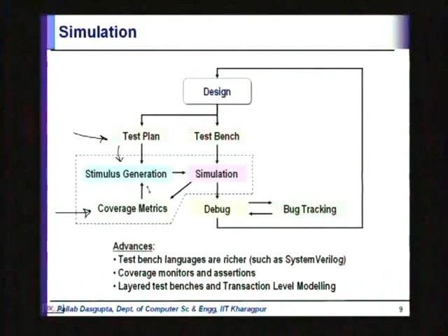It can even do things like state coverage, whether every state bit has toggled once, that is toggle coverage. Whether certain wires have toggled at least once during the simulation, that is toggle coverage over the signals. So, there are different types of coverage metrics like this, and those coverage metrics are monitored all the time during simulation.